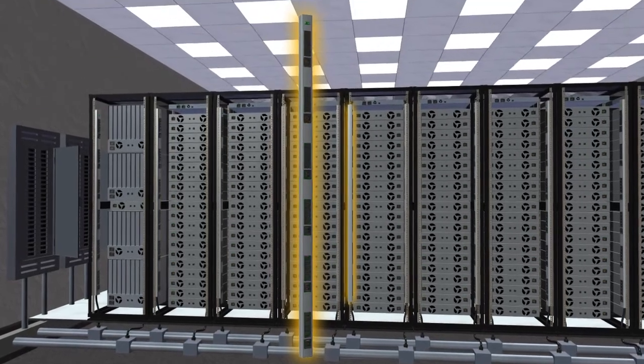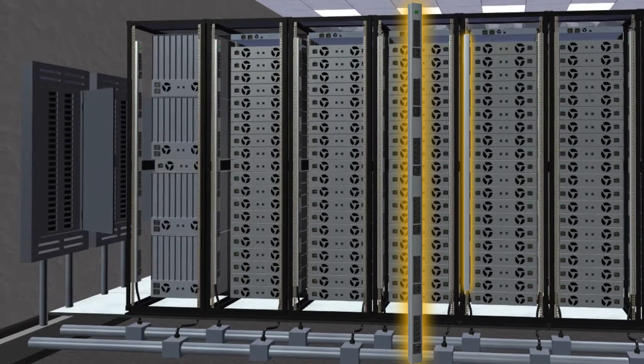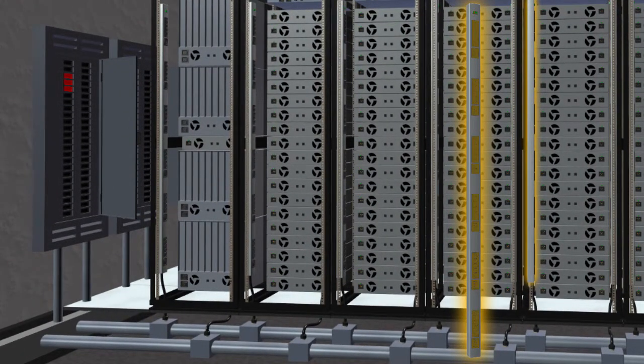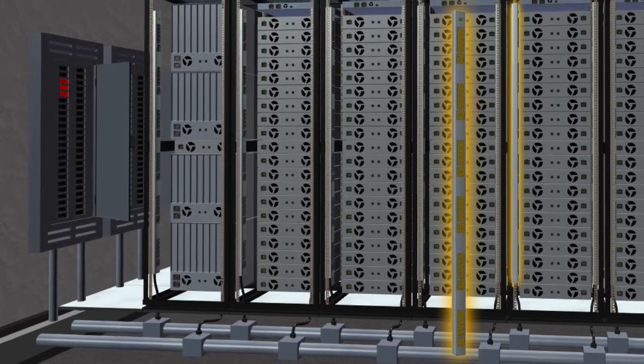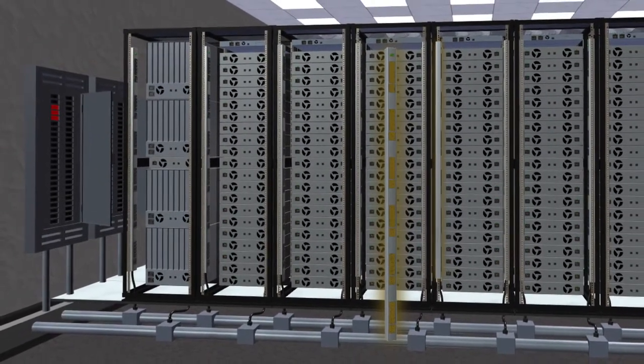This is in contrast to a multi-phase plug strip connected into a power whip or busway tap box, where a trip of one breaker forces all of the circuit breakers protecting the outlet to trip, completely de-energizing the plug strip.